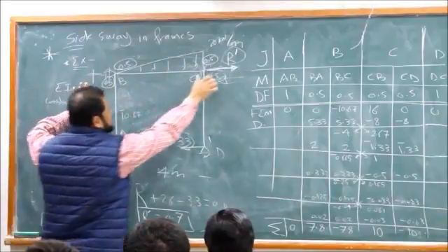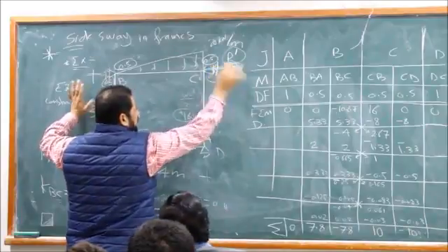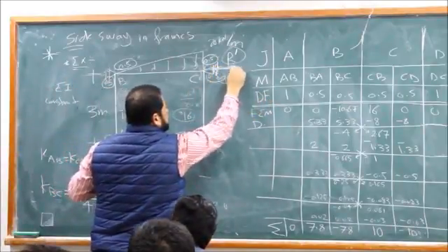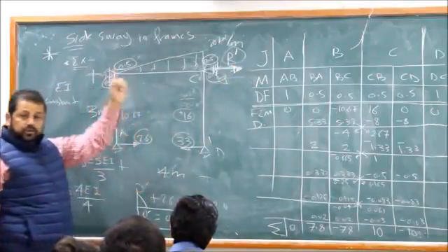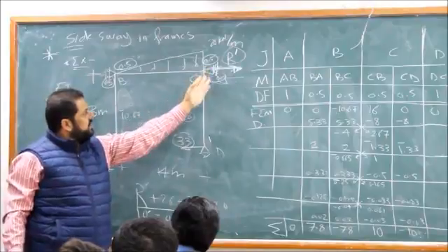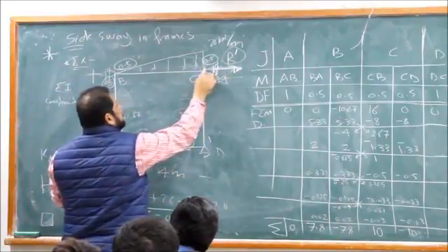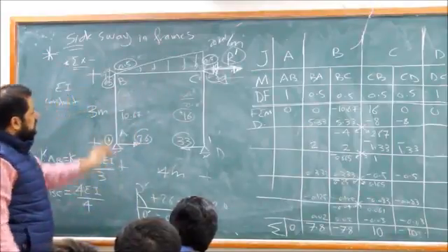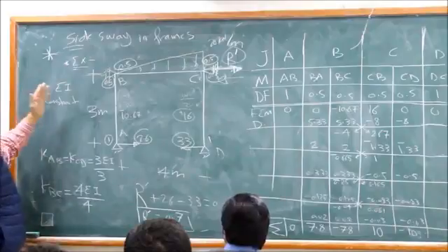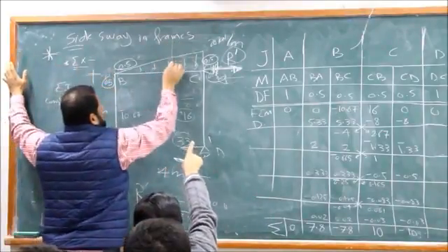But according to this answer here, there is a reaction developed here. To do this, you prevented the movement by this reaction and the reaction here. So when you solve your truss, you have to apply the reaction in the other direction. You have to apply the same amount of R dash in the other direction, because the resultant of the load here will be closer to it.